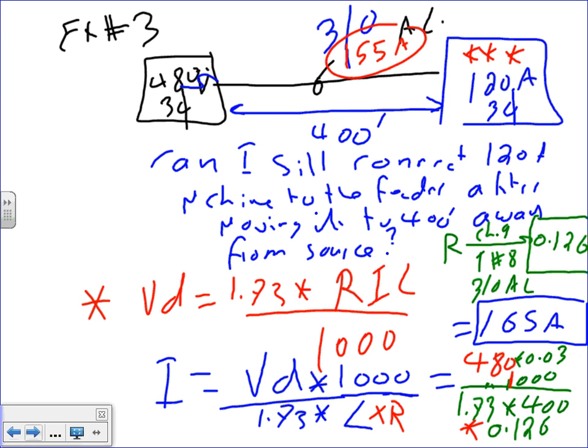See what I did? Forget about everything else. Find the voltage drop for this problem. Three phase, 3-aught with a voltage of 480. If you do the voltage drop on this problem, it's 2.8. Is this a problem, percent? No, we don't have a problem. And that proves it. I don't have a problem.